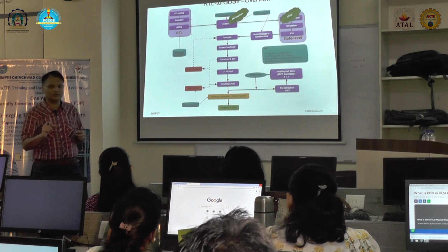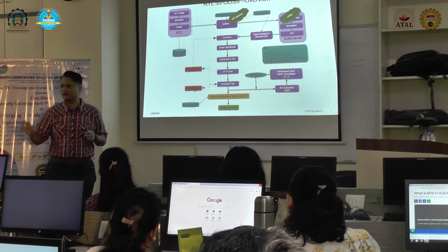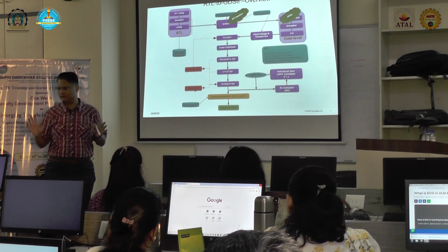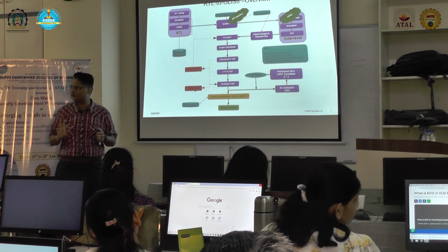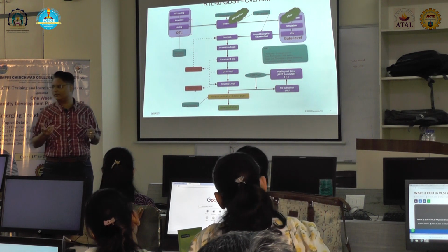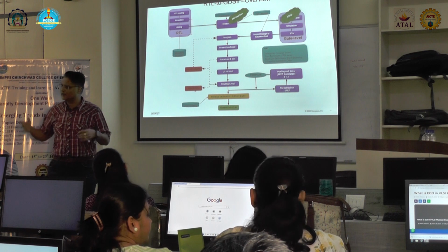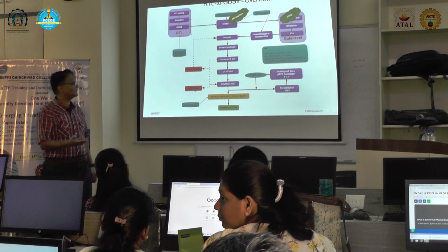And even if somebody wants to use it, they will say upfront that okay, yield is 50%. You choose whether you want to take it or not. You will have to pay us for 100 chips. Even if 50 chips are faulty, you have to pay us for those 100 chips. So it's a decision that the design house can make. If you really need that node, if I cannot work with anything other than 20 angstrom, then I have to make that first. So things like that.